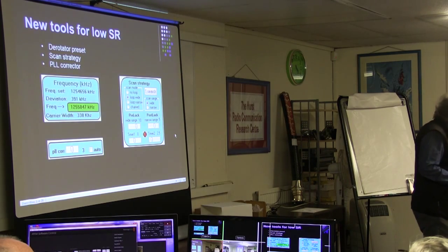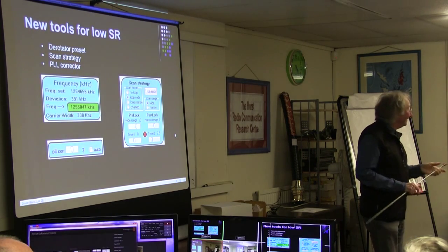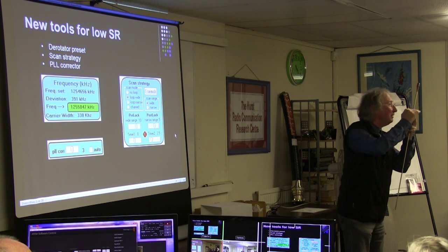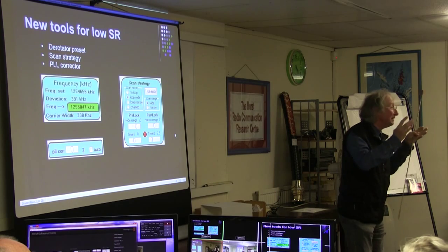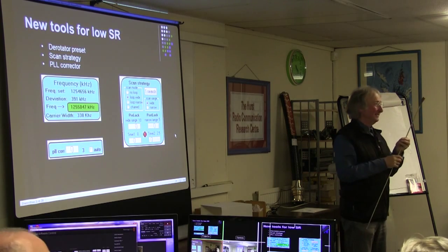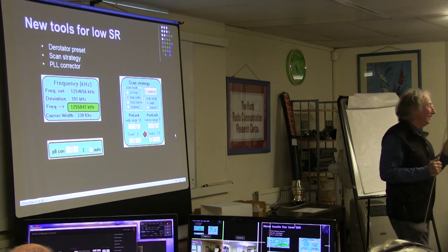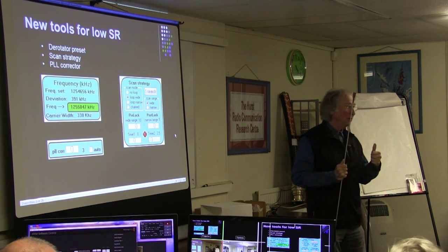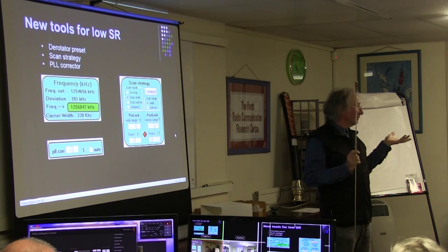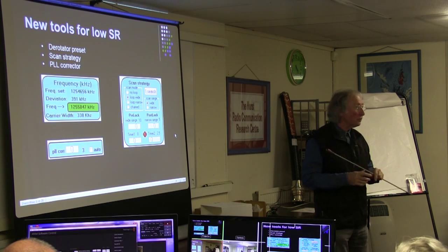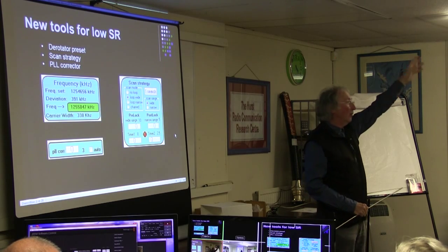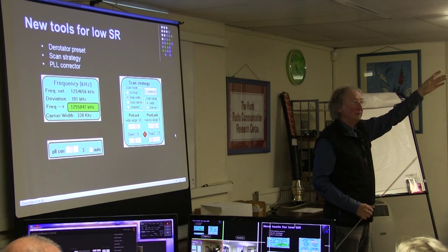very little signal in the noise. And with the QSB, sometimes you lock on it, sometimes you lose it, you lock on it. So, when you have locked the first time on a signal, you do not have to search 1 megahertz or 100 kilohertz away if it comes back.